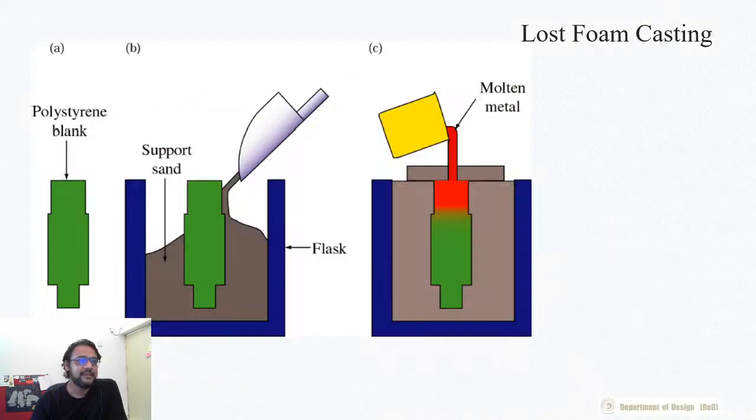Okay, right. So a variation of this, instead of using wax, you could use something like thermocol. The thing about thermocol is that if you directly pour molten material on top of it, the molten material would heat and eat away the thermocol, and it would become impurities within the molten material itself. But it's such a small volume that if you're casting very large parts, this is a good enough process, right?